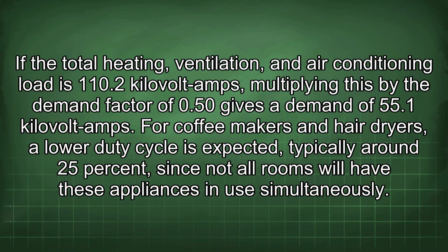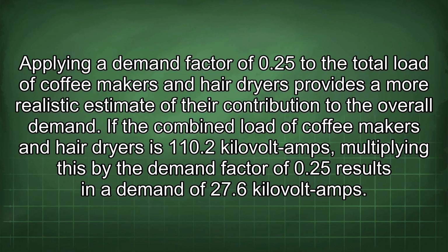For coffee makers and hairdryers, a low duty cycle is expected, typically around 25%, since not all rooms will have these appliances in use simultaneously. Applying a demand factor of 0.25 to the total load of coffee makers and hairdryers provides a more realistic estimate of their contribution to the overall demand. If the combined load of coffee makers and hairdryers is 110.2 kVA, multiplying this by the demand factor of 0.25 results in a demand of 27.6 kVA.